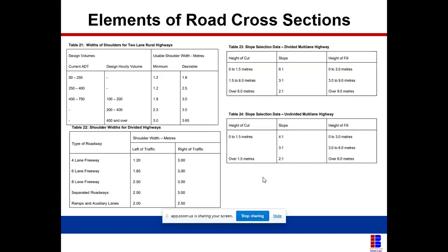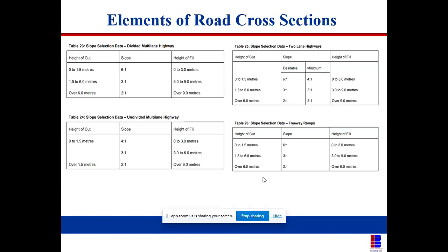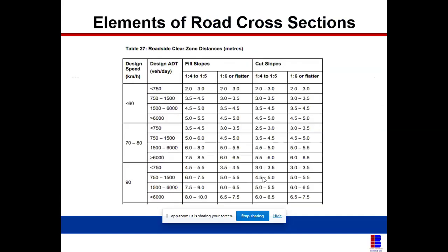If you're having a high fill, when you have to cut, you cut between 1 to 2 slope. You cut, whether in benches or with the direct slope that comes down and is trapped with that drain at the toe of the embankment. The same thing as well, that guides your cut and filling when you are cutting on your road, having high fill, high cuts and all. So you use the slopes 4 to 1, 1 to 2, 1 to 3 and all. So this will guide you when you're doing that. So elements as well, fill and all the traffic.